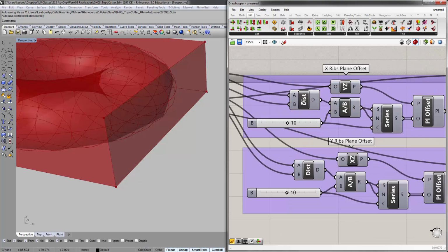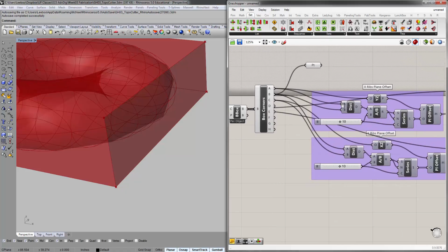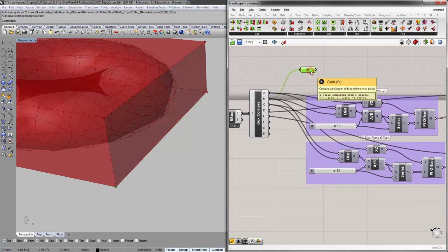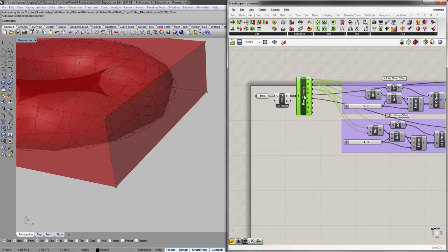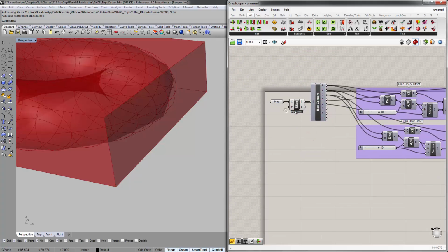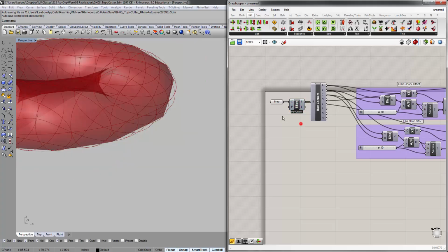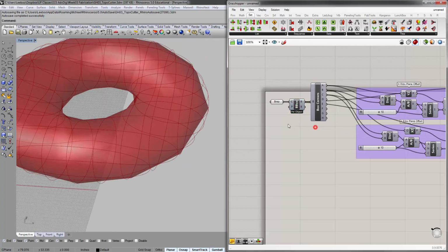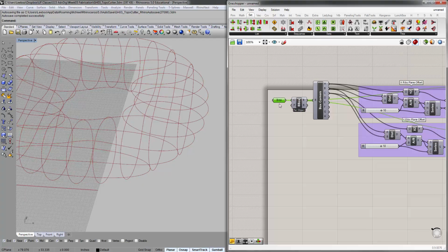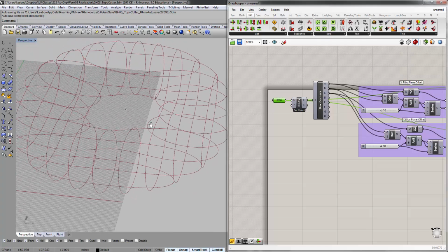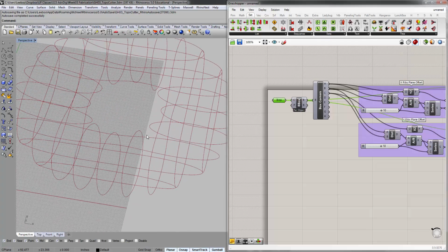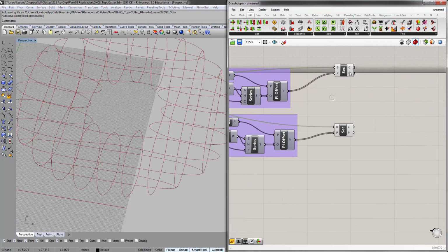If you see a component that's gray, that means its preview is hidden, and I don't need this anymore. We don't need the bounding box to show up either. If you want, you can hide the BRep as well, but you'll see that we're getting all these section curves now. These are the section curves that we really want.